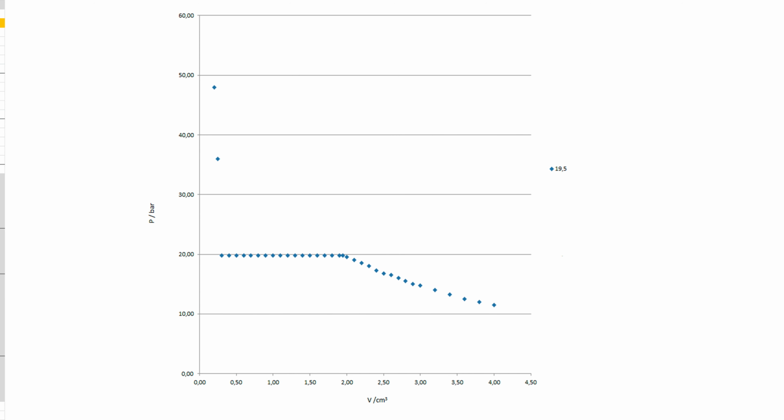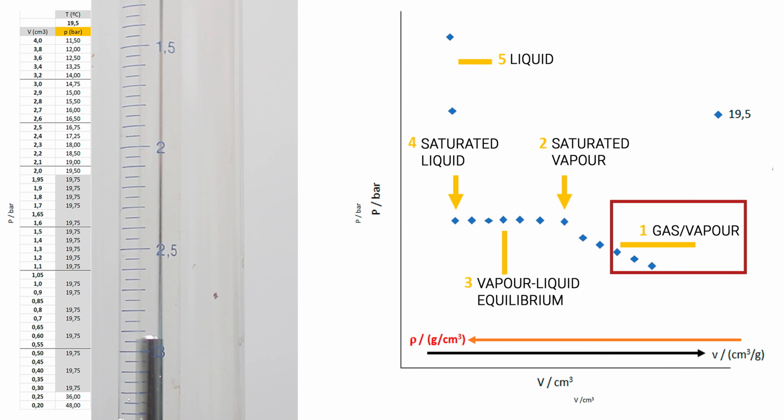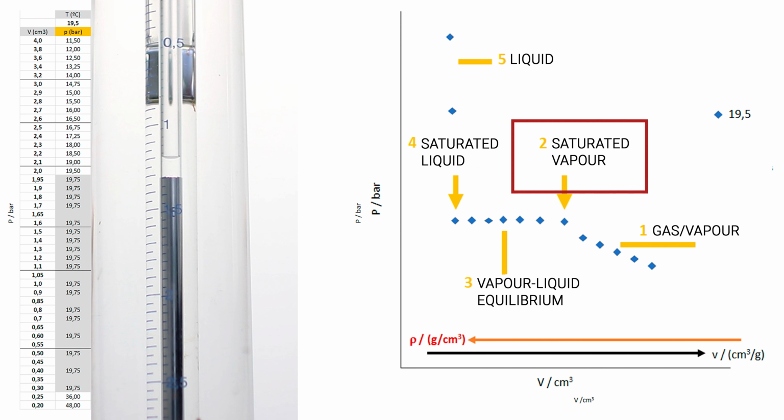Thus, we can reinterpret the results in terms of density. The following can be observed. The gas region, in which the fluid suffers a smooth increase in pressure as the density is increased at constant temperature. This region is called the superheated vapor region. The appearance of the first drop of condensed liquid. We can state that the gas at this pressure and temperature has saturated its capacity of maintaining all its molecules in gas state, grouping some molecules in the first liquid drop. We denote this state as saturated vapor or saturated gas state, which represents the density of the corresponding saturated vapor.